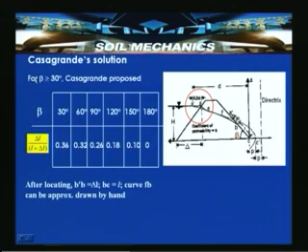In case of beta greater than or equal to 30 degrees, Casagrande proposed an approximation, which is the distance delta L, that is this distance here, and L. So, from the directrix, the location is given by delta L by L plus delta L for different betas. For 30 degrees, delta L by L plus delta L is around 0.36, for 60 degrees around 0.32, for 90 degrees around 0.26, around 150 degrees beta it is around 0.1 and for 180 degrees beta it is around 0.